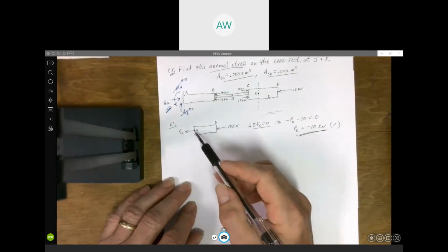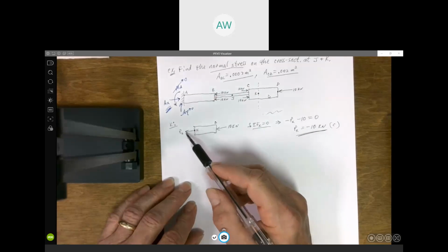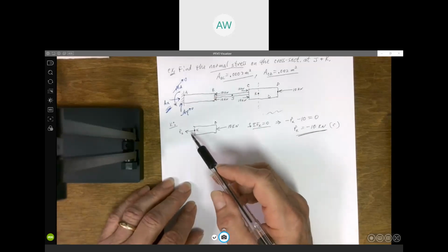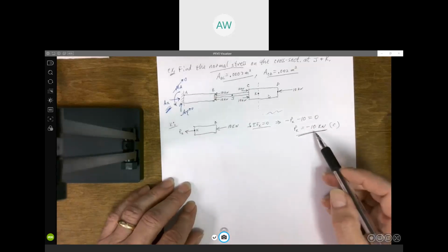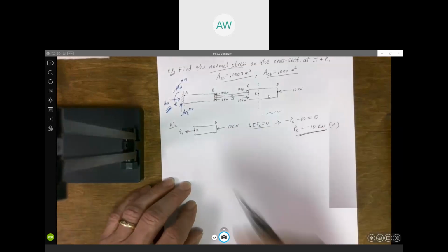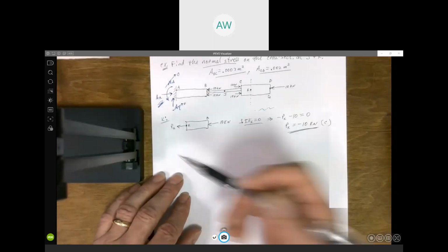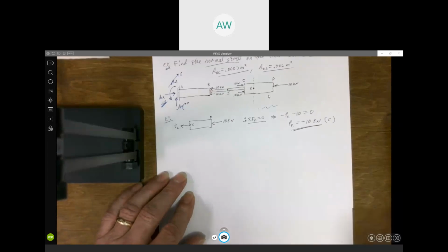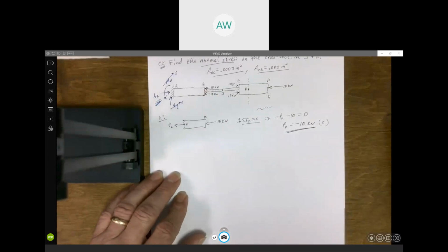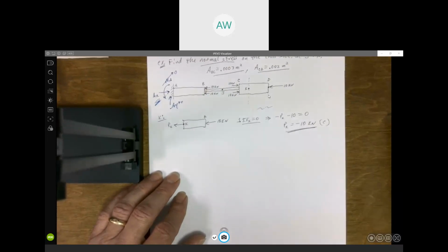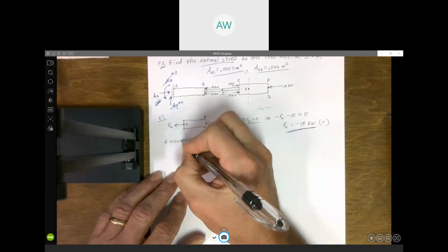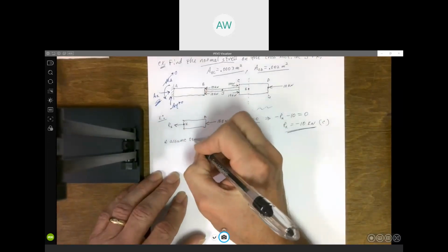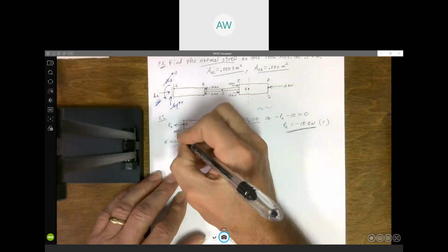going back to what we did yesterday, you could assume this axial force is going whichever direction you want. We could assume it was going to the right. We would have got P at K here is positive. But I intentionally assumed it was going this direction for a reason. Again, this goes back to, I don't know when you took statics, when you did trusses, but when I teach statics and trusses, I tell my class to assume tension. And that's what I'm going to recommend here. So assume tension here as far as the direction goes.